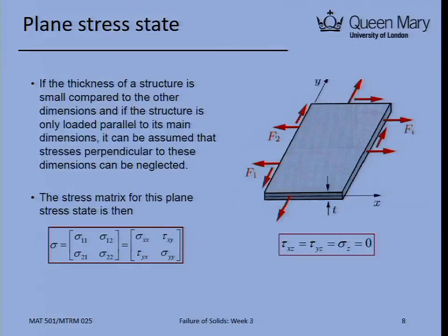The through thickness direction is almost nothing. If you load that, suppose the Poisson ratio causes some contraction in the through thickness direction, but because the thickness is so small, you generate nothing in stress.